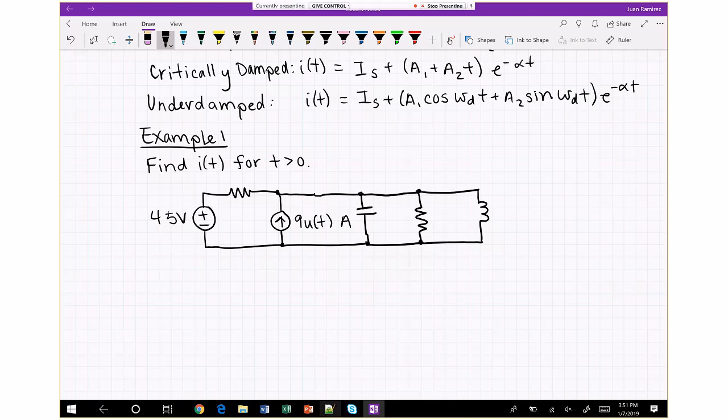And then if we're thinking about current sources, with a switch in parallel with a current source, when the switch is open, you have regular current going through. When the switch is closed, that current source looks like a short circuit. Whereas with a step input for a current source, when it's high, it's supplying current normally. When it's low at 0 amps, it's represented by an open circuit. So just make sure you remember those 4 different scenarios.